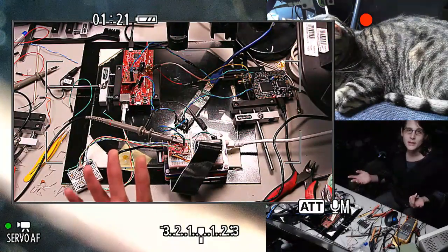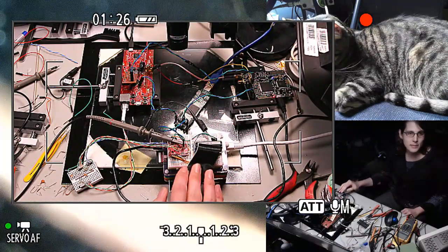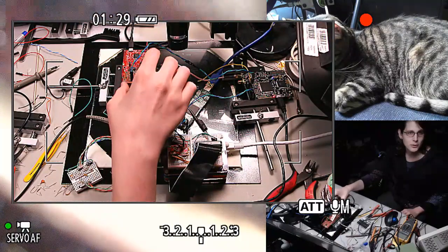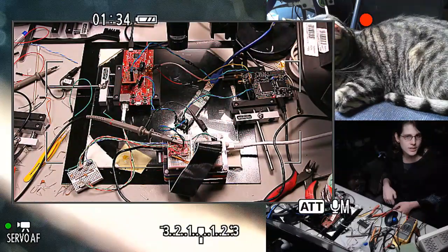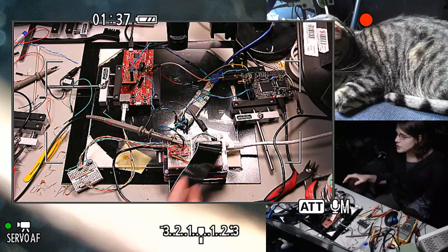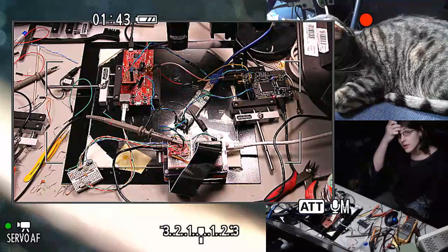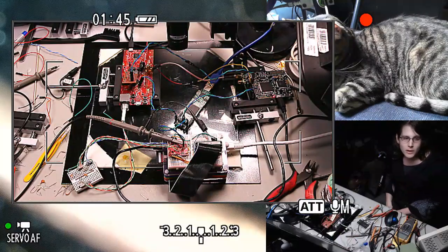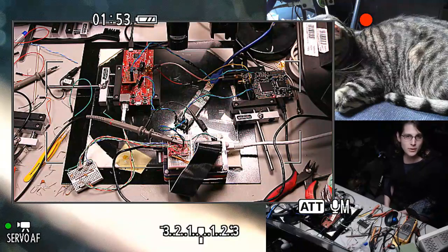Because I'm focusing on initiating the test from this Raspberry Pi and sending packets over this Ethernet interface to this microcontroller, having it respond to those packets, and then along the way doing electrical glitches. So I've got this set up so I'm initiating it from this side. So far, and to go back even further, I do have this whole thing working with a modest only 25% underclock at 30 megahertz, but I want to go lower because it's still inconvenient to do nice steep glitching pulses at the frequencies I'd want for a 30 megahertz CPU core.